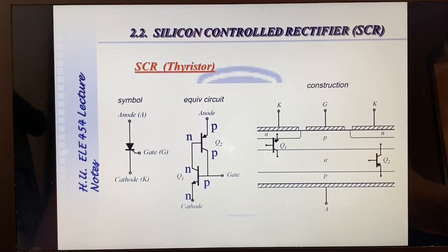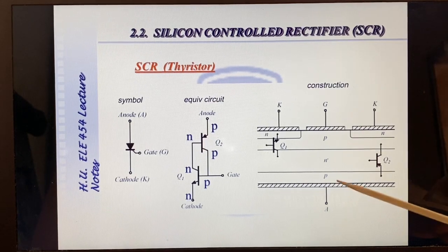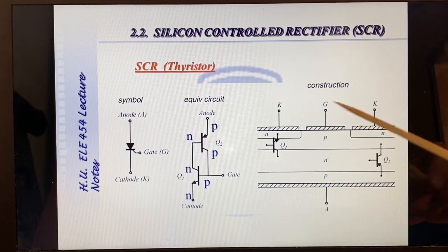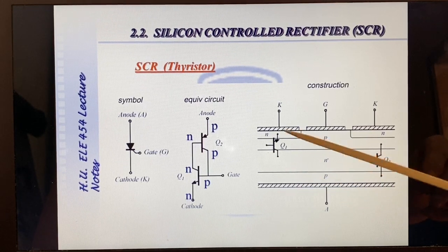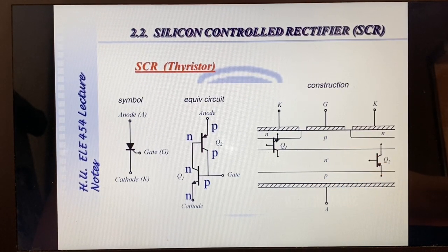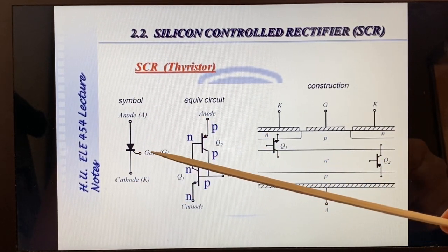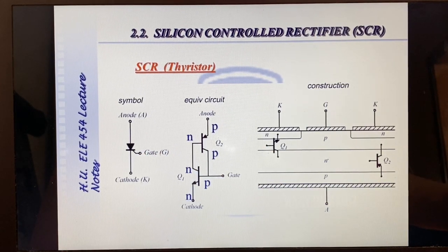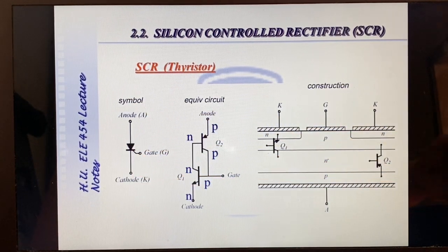Now let us continue with the silicon controlled rectifier. In some versions, it is like a controlled diode, but it is different from a diode. It is a PN junction device. Within this chip, you have many such parallel PN constructions, where the equivalent circuit and the symbol are represented here. With a control voltage taken from the cathode here, the gate to cathode current will trigger a forward biased thyristor into conduction.